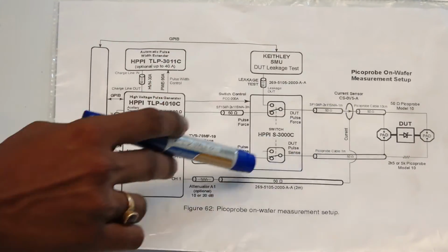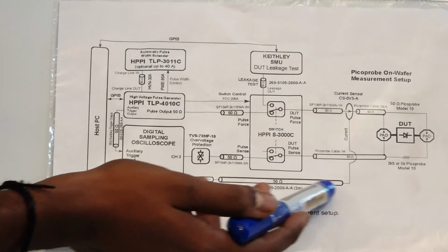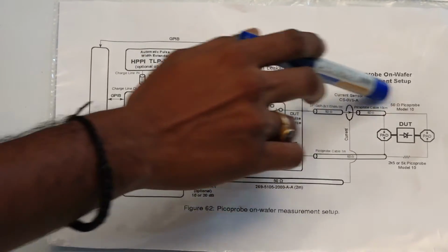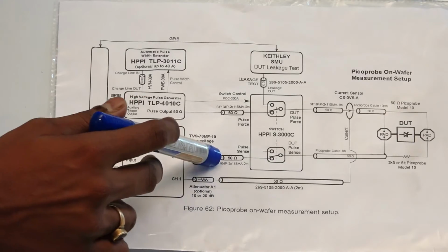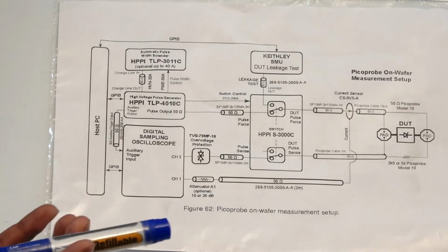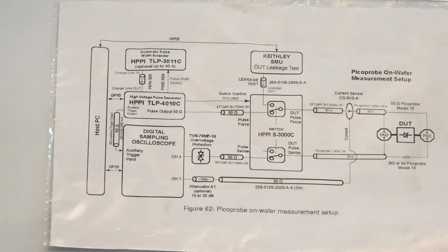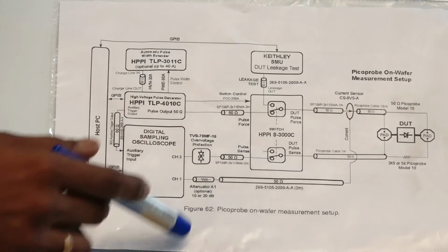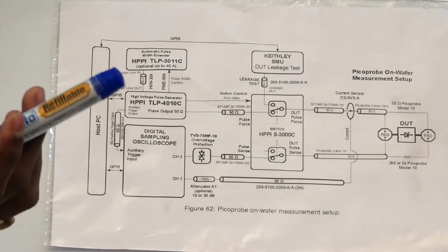The current sensor is very important, because if your current sensor is faulty or not up to the mark, you'll not be able to measure any voltage current waveforms. Then these transmission lines become important. Then you have these attenuators here and the oscilloscope inputs. Using these attenuators is pretty common, however it's not necessary. The reason we use these attenuators is because these oscilloscopes can only take a voltage input of 5 volts, and if your input is going to be higher than that, you would have to use these attenuators. And we'll take these attenuators into consideration when we start talking about calibration as well.